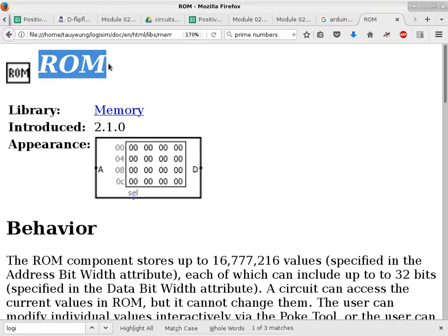So the next generation are called EPROMs. E stands for erasable. So now we have erasable, programmable, read-only memory. That should sound really confusing. So the erasable ones look like this. It's a chip, rectangular in shape, pins coming out from both sides, and this one has got an optical window in the center. Usually it is round in shape. Occasionally it is kind of rectangular in shape, but doesn't matter.